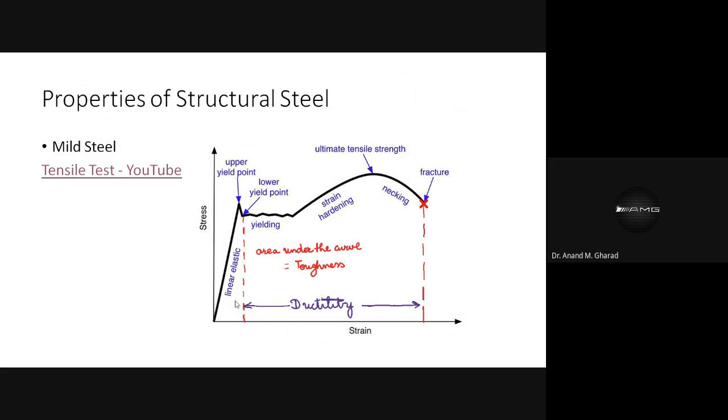That is the capacity or ductility. And if we are in a position to explore this, then we are allowing that material to use its full capacity, full strength. We are not restricting it to the elastic limit itself, and that too by applying a permissible limit. So this is the summary, you can say, for the limit state design method.